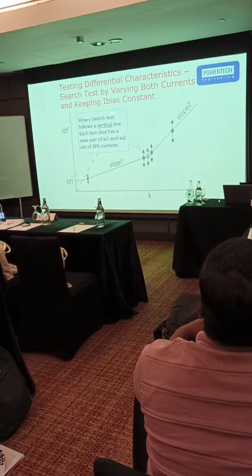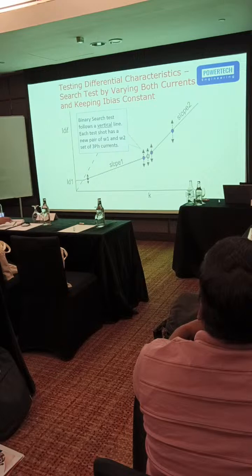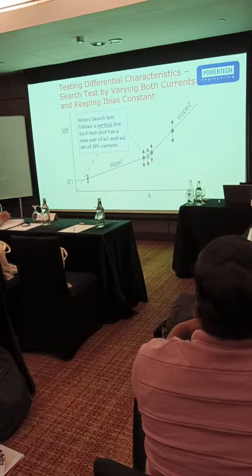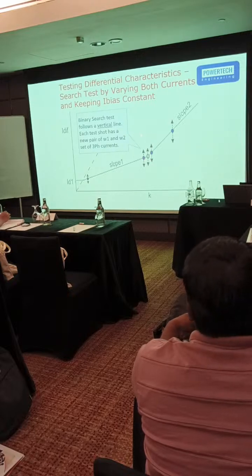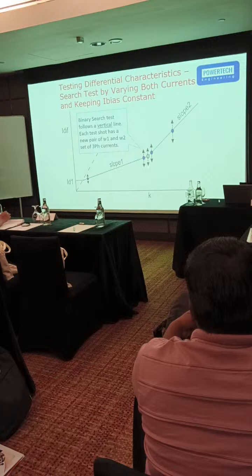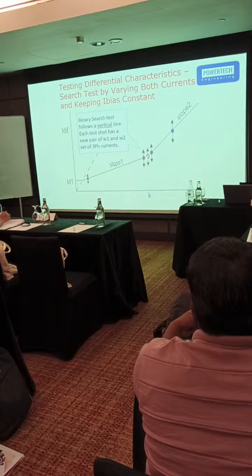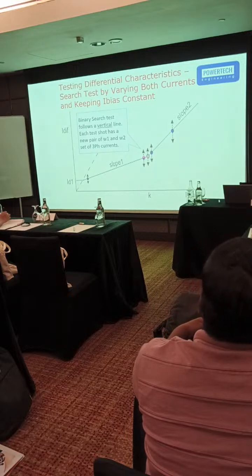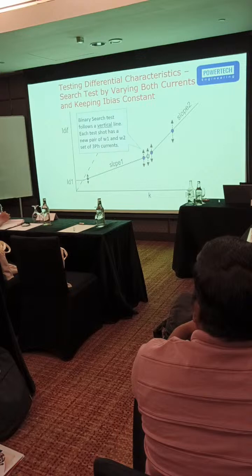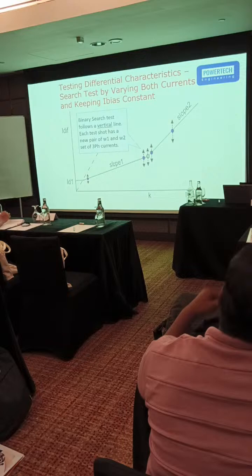This is called binary search. One point is injected; if it has tripped, then they inject the other point up and down, depending on whether it is the non-operating region or the operating region. The point always moves from below to above. If the relay tripped, that means you got the boundary point. So they reduce the current slightly. The first step to find the current is bigger.